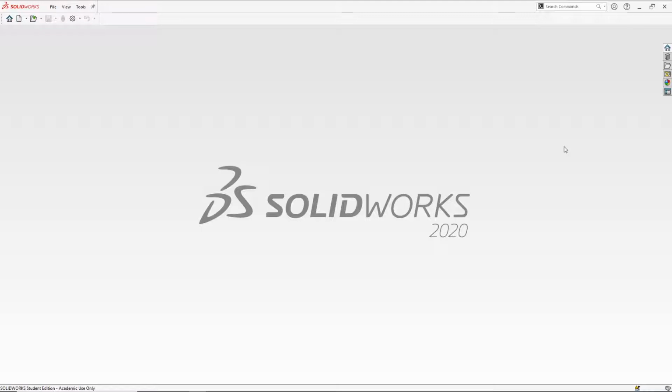This video shows how to model the 6 pieces of the Bauhaus chess set from 1924 by Josef Hartwig using 6 separate SolidWorks parts. The pawn of this chess set is a cube with an edge length of 19 mm. To be able to state that value of 19 mm only once and reference it in sketches and features, we are going to use a global variable.